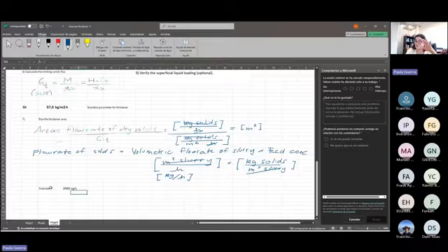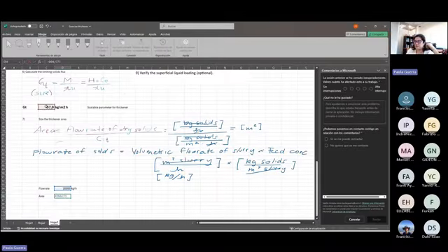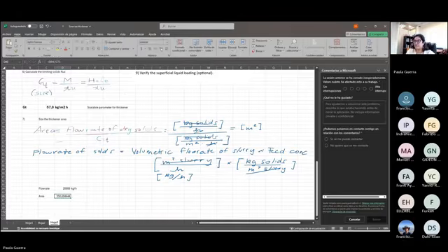Okay. So now we can calculate the area as the flow rate of solids divided by the GT that we calculated in our first exercise. So that's what I mean by this being the scalable parameter for the thickener. So this is going to be 351 square meters.